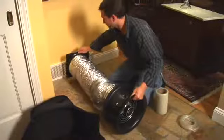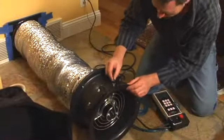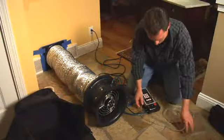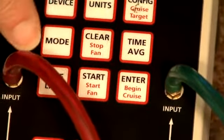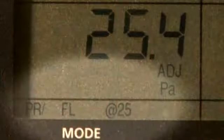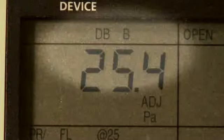Next, connect the duct blower to the duct system. You can connect to a major trunk line, to the air handler, or to a central return grill. Here, we're connecting it to the return grill. Now turn the manometer on and hit the mode button 3 times until it reads flow at 25. Be sure you're reading for a duct blower by pressing the device button until it reads duct blower B.